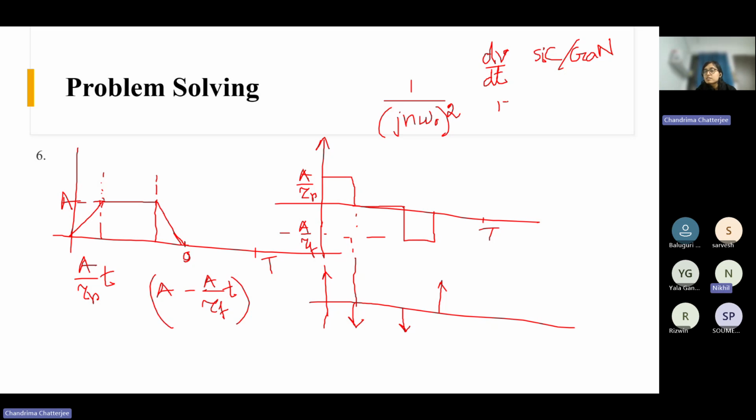But if you know, I will just tell you, maybe you already know this. We were discussing the frequency range where we consider the EMI starts. What I know is 150 kilohertz to 30 megahertz, right? There may be some other ranges also based on the application. But if we consider this one, I have seen people making converters where they choose their switching frequency. As we increase the switching frequency, our passive size decreases, right? That is one advantage of increasing our switching frequency.